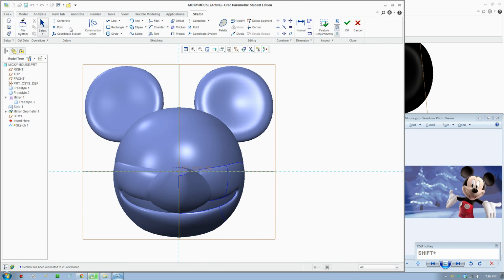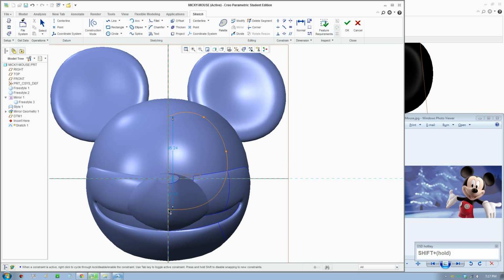Okay, now we just create the little line at the top. To do that, just go to which tool? Click on the spline tool here. Make sure you click on the center line, and draw that shape. Press the middle mouse button to accept, and also just go in quickly add some adjustment there. And the eyes should be slightly more to the right. Okay, just draw like that.